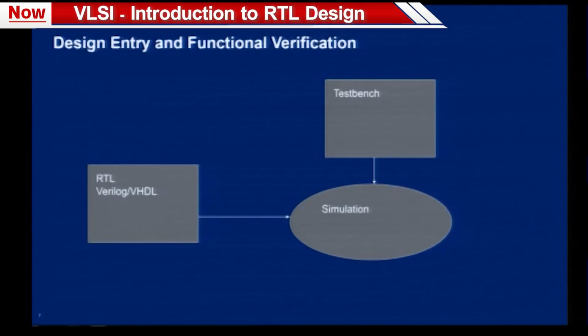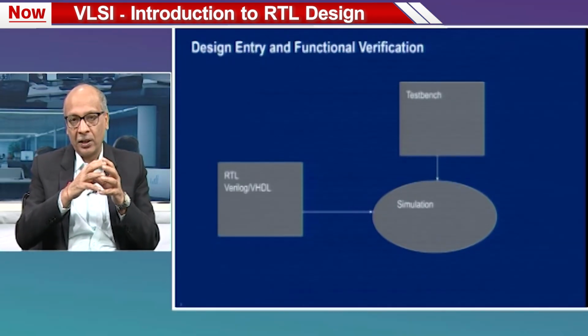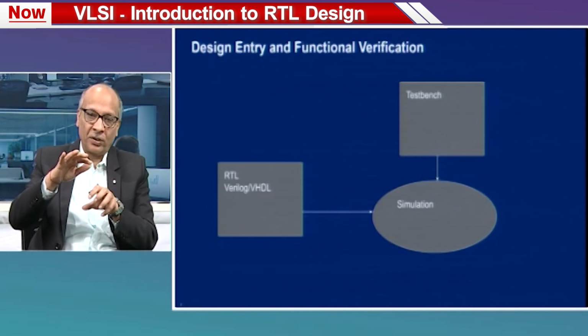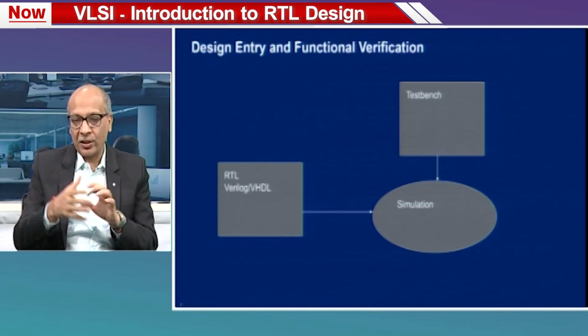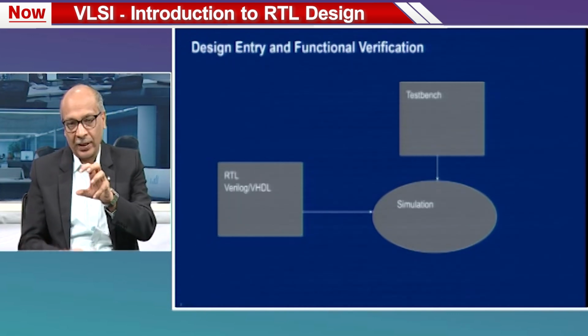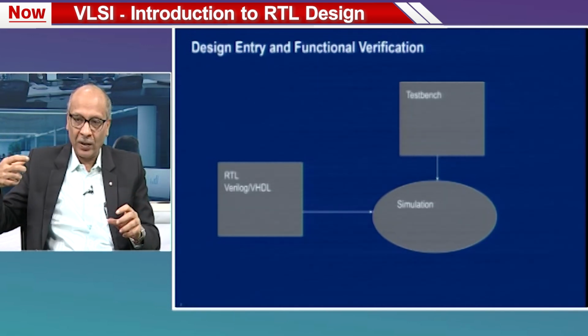So, fundamentally this is what we are talking about. We write the RTL in Verilog or VHDL, both of which are called HDL languages, and we write a test bench. Test bench is the one which is applying vectors at the input. Vectors means zeros and ones. For example, if you have written an RTL for a counter, your vectors could just be repeated clocks. And simulation is the process where the simulator tool is used, where we read the RTL design and the vectors, and the simulator tool will tell us what the corresponding outputs will be.